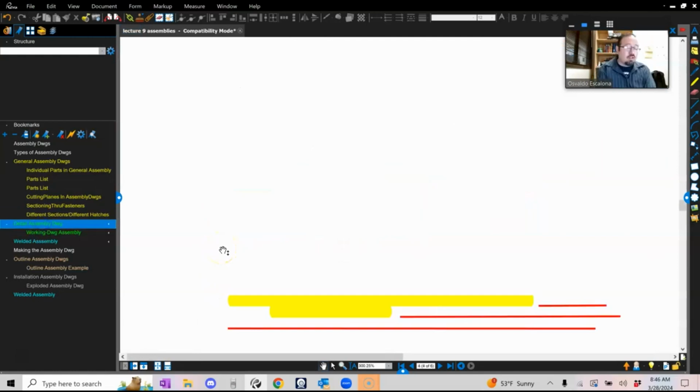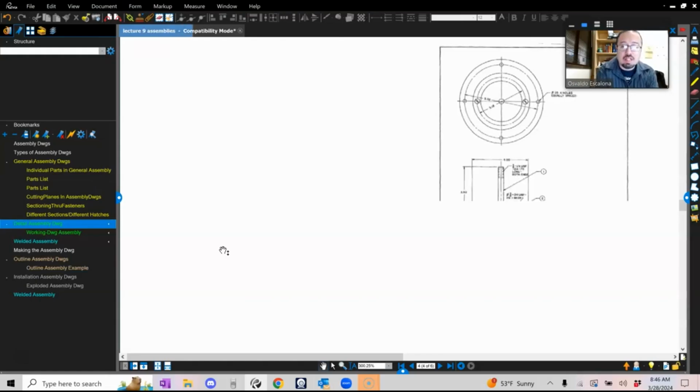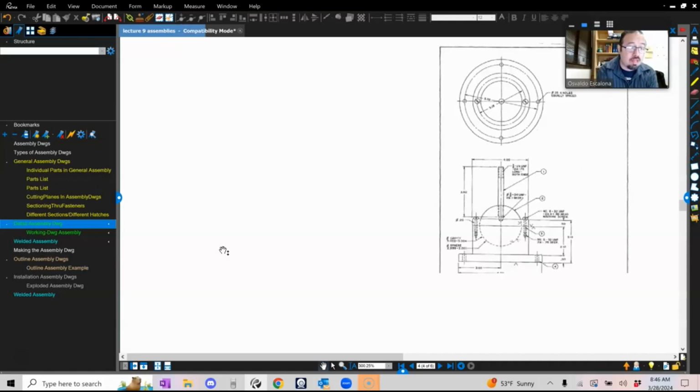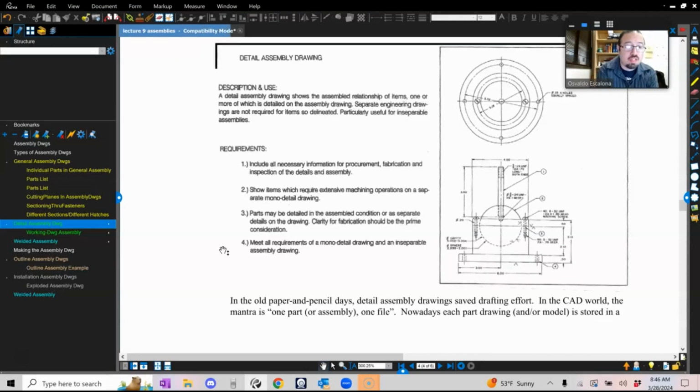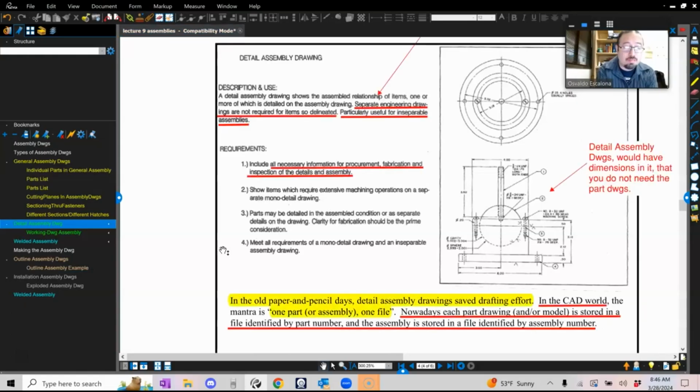Let's move into a different one. Okay, so for assembly drawings, you have different parts. You might have sub-assemblies as well inside of it. Each of the parts in each of these sub-assemblies will be in a part list. Each of the parts that you show in the assembly will have a bubble. The dimensions that you get to put in that assembly are only going to be for assembly conditions, instructions for the people that assemble things together. If you give other dimensions, they should be reference dimensions.